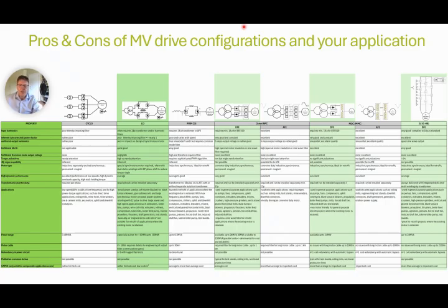However, when used with a direct front end DFE, depending on the short-circuit ratio, these drives generally require an 18 pulse in-feed to comply with IEEE 519. The 2-level series Cascaded H-bridge provides clean input power thanks to the cancellation of harmonics by phase displacement. We have a multi-pulse input ranging from 18 to 54.